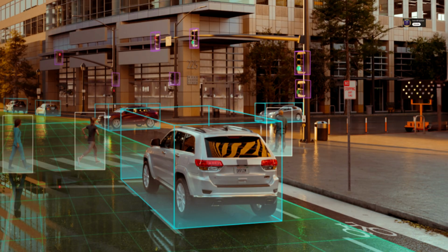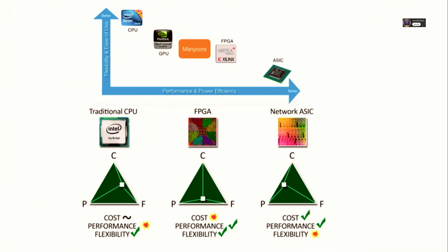Yeah. Okay, now let's shift to the big financial trade-off. The battle between the FPGA and the ASIC. If FPGAs are so flexible, reprogrammable, updatable in the field, why on earth would a company swallow that massive upfront cost and inflexibility of an ASIC? Yeah, it comes down to two things mainly. Scale, and that huge financial hurdle we mentioned. NRE, the non-recurring engineering costs.